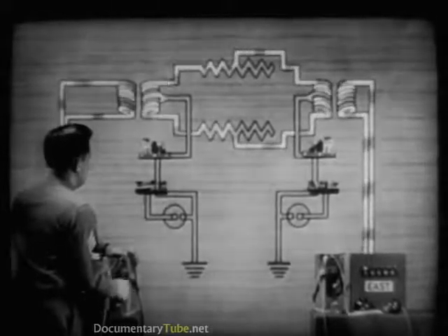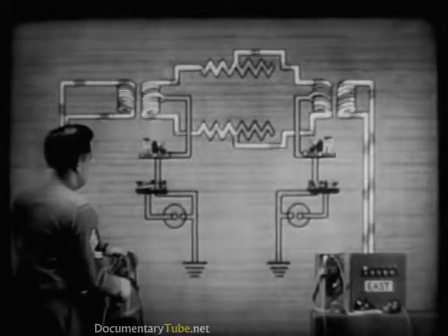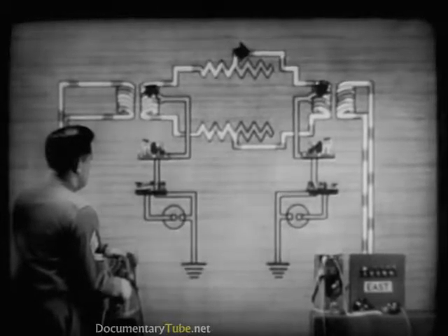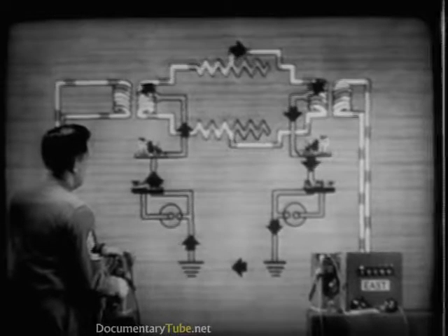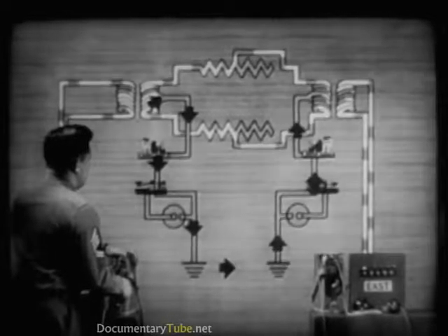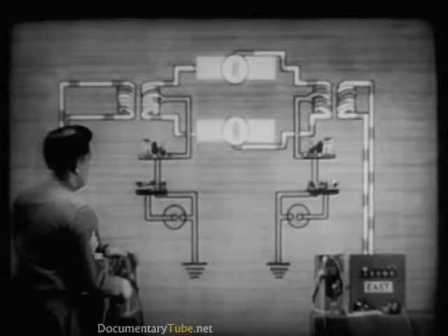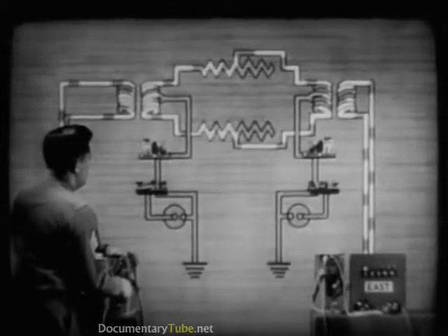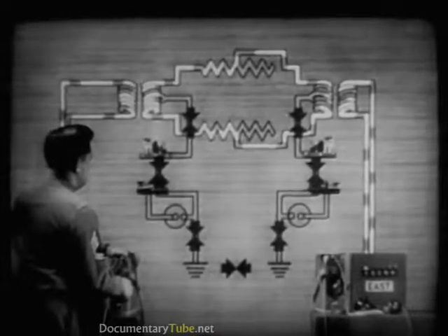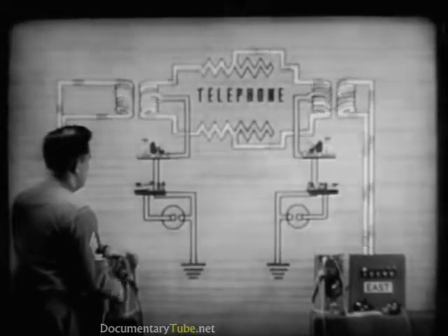What prevents the telegraph sets from receiving telephone current? Let's freeze that current again. The upper half of the winding is trying to send current through this path. And the lower half of the winding is trying to send current through this path. Since the resistances of the two line wires are equal, two equal currents are trying to flow in opposite directions through the telegraph sets. They buck each other and no current flows. Consequently, the telephone circuit doesn't interfere with the telegraph.